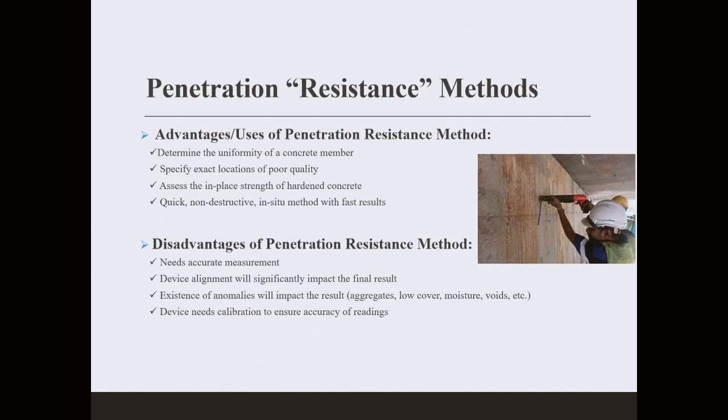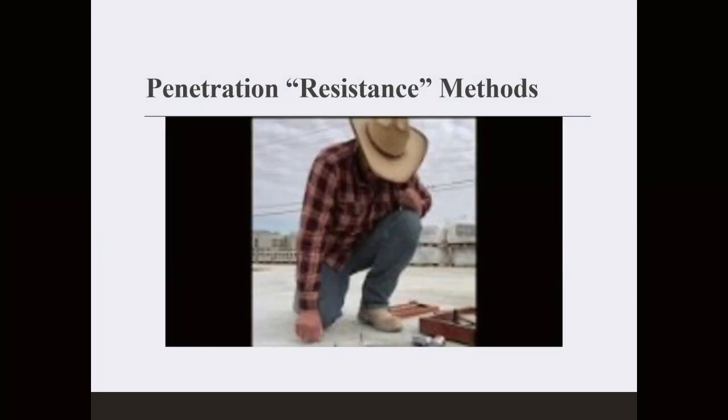So in order to get yourself out of this problem, always think about conducting 5, 6, 7 tests for any given section, and then you take averages. One of the methods: you calculate the average, you add 20% plus or 20% minus, you go back, and any result that doesn't fall within the plus and minus 20%, throw it away. The remaining results, do the average for them, and this will be your final value.